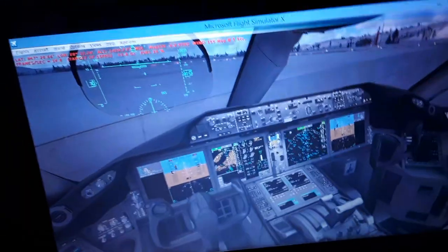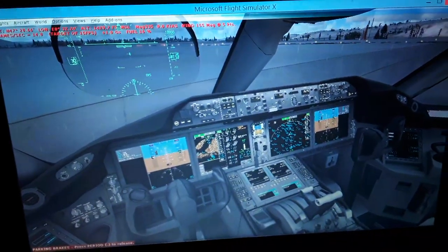That displays the airspeed indicator, the airspeed selected from the autopilot director system panel, the ground speed, the radio altitude above the ground level, the barometric altitude above the sea level, the barometric pressure of the outside atmosphere, and the target altitude selected from the autopilot and flight director system panel. We have also the vertical rate of climb of the aircraft in tens, hundreds, and thousands of feet per minute.